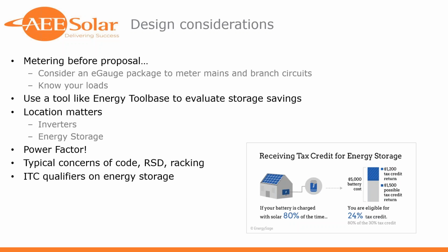I'll say location matters, just real high level. You've got to do a little bit more thinking about where you're siting, where you're locating the inverters, and obviously the energy storage and the impacts that will have, temperature-wise, voltage and cabling-wise. Again, this goes back to metering, doing a brief site audit, figuring out what you have to work with on these projects.